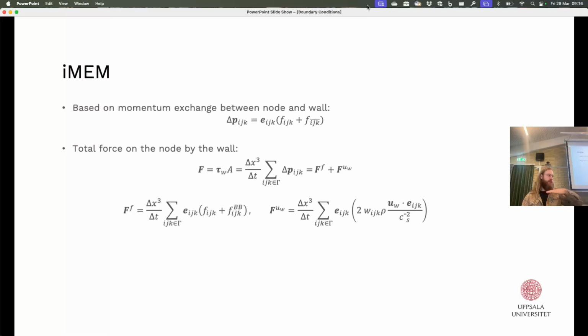So there are also other approaches where they do it a bit simpler. They just say, well, the wall shear stress times the area is the force, and then they just impose a drag force on the first node. Kind of a similar idea. I think ours is a little bit more valid because we actually place the force at the ground instead of the first node, but yes.